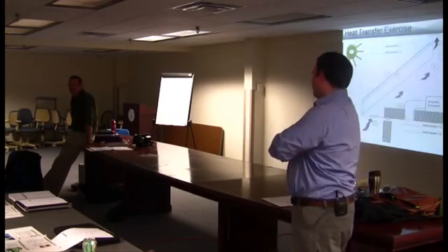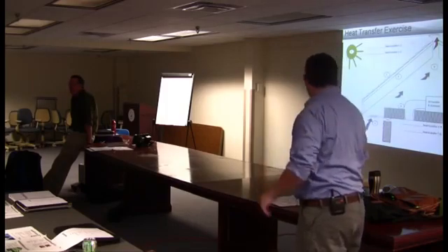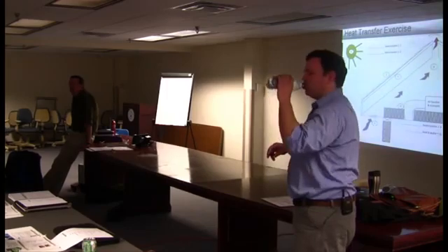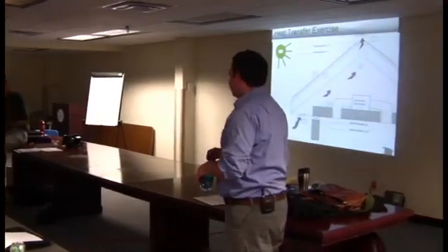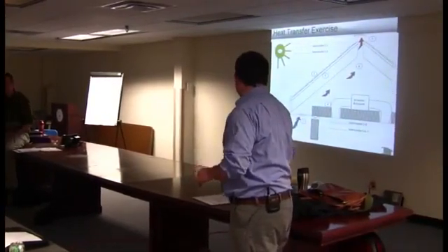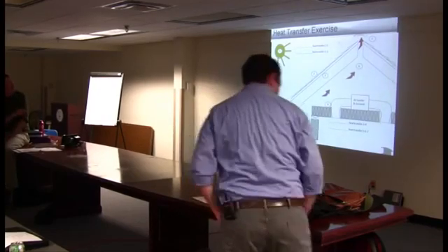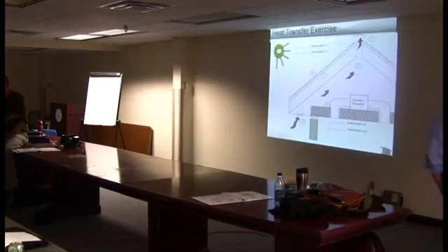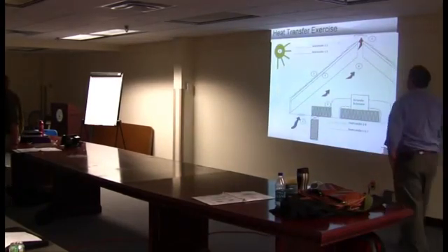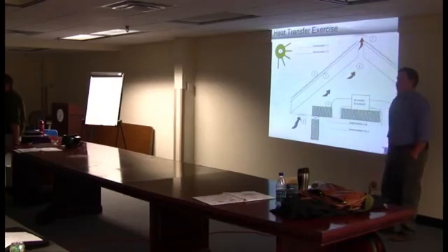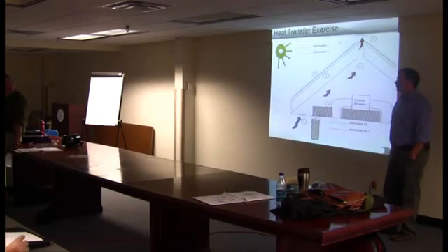So if you were here Monday, you saw this, a little exercise in heat transfer. Here's a kind of, this could be a commercial building, but it's sort of a residential style attic assembly, where the energy is traveling from the sun to the shingles on the roof. What type of heat transfer is that? It's going through space, right? There's no fluid in there, and there's nothing solid, so it has to be radiation, right? Okay. All right. What next, Burke?